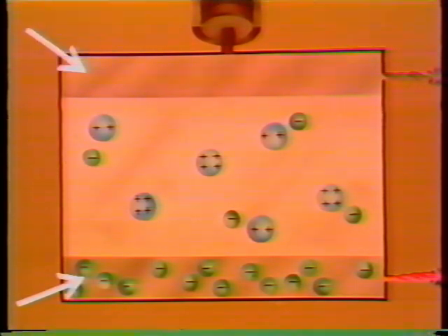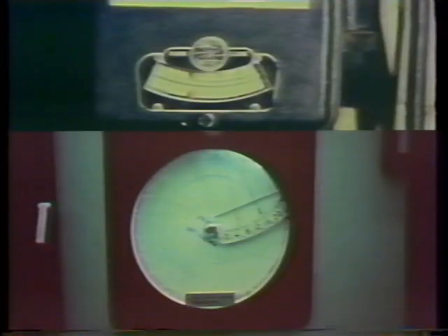The electrons accumulate on one of the metal plates, giving it a negative charge. The amount of difference between the negatively charged plate and the other plate is the amount of voltage produced. So the voltage is proportional to the pressure that's being measured. That's why it can be used to operate meters and recorders to indicate exactly how much pressure there is in the system, or initiate alarms if an abnormal pressure occurs.